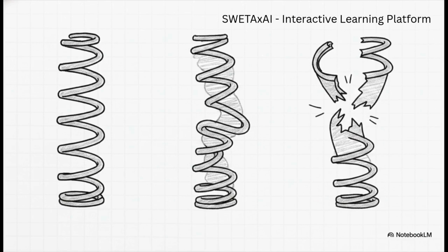But you have to watch out for this trap on the stress-strain curve. There is a massive difference between the yield point and the breaking point. If you push a material past its elastic limit and hit that yield point, you enter the plastic region. That means permanent deformation. It's never going back to its original shape, even before it actually snaps at the breaking point. Keep those definitions sharp.